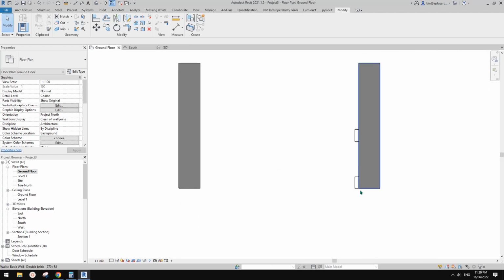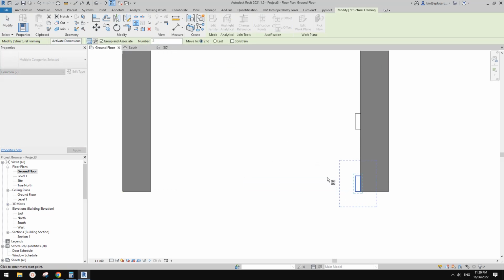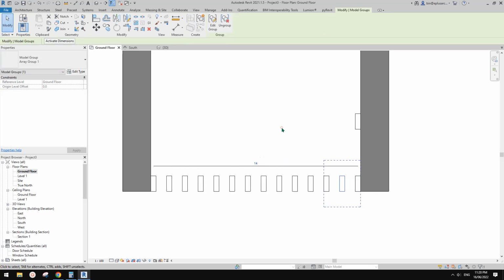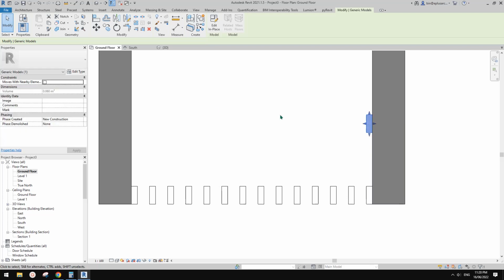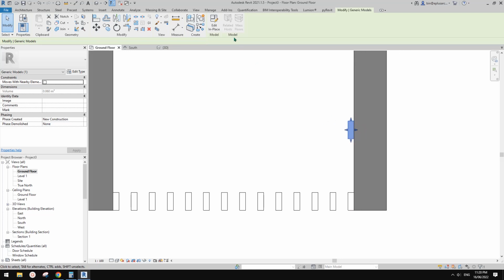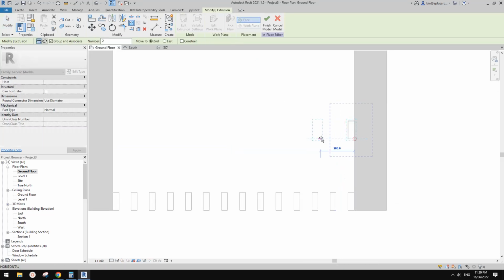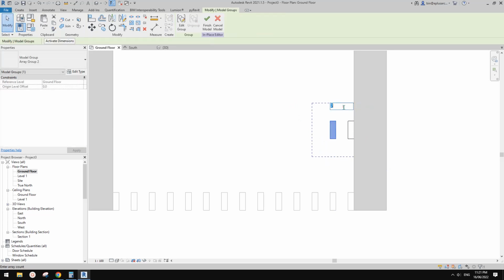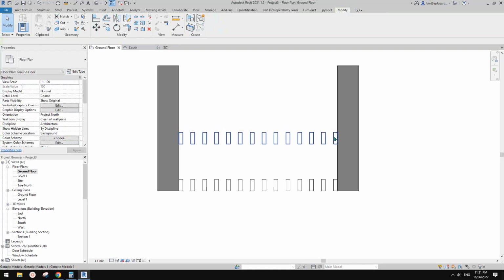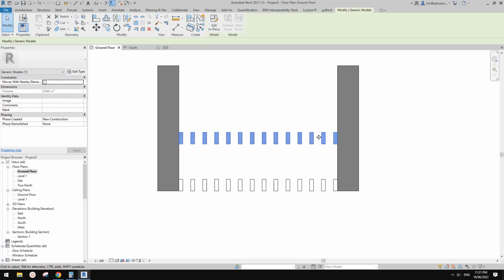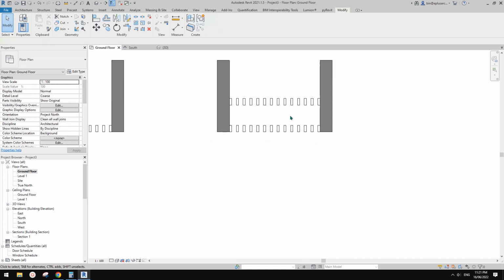Okay, so go back to ground floor plan, AR array. So you can choose second, just type in 150, type 13 or 12, I think, 13 or 14. Yeah, that's it. Done. Same, this is a generic model. And also if it's a generic model with one element, maybe just edit in place and do the array in the generic model. Okay, so 14, finish, because this will create one element. But sometimes you can just array outside of the modeling place, but you will create multiple families, multiple model in place. Sometimes it's a little bit messy.